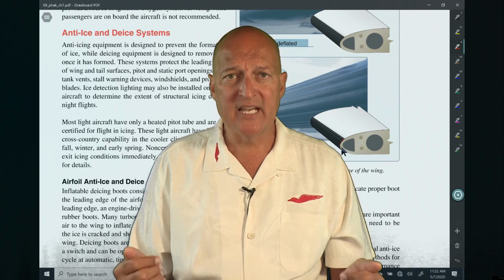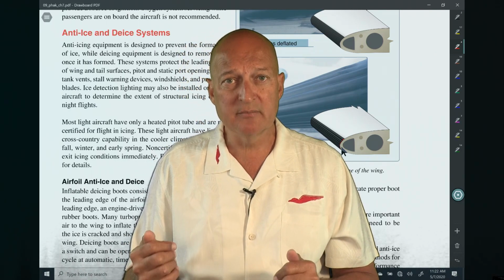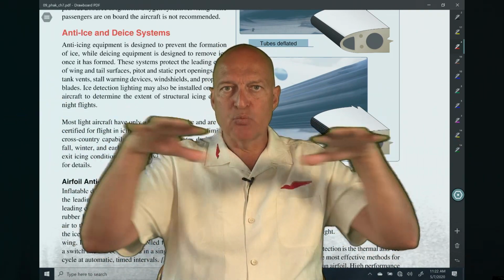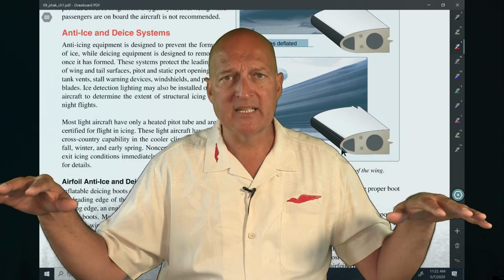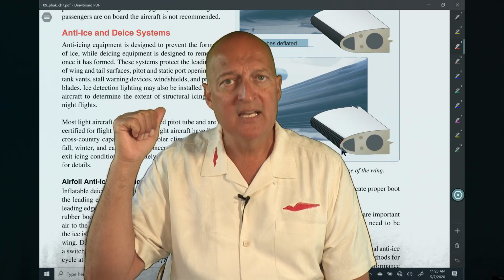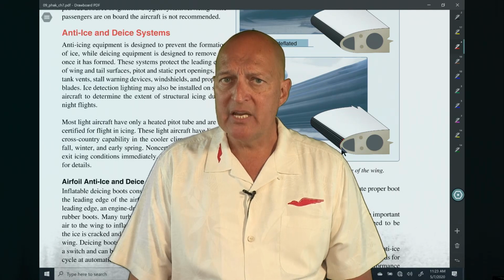Now your airplane is heavier. Think that might also have an issue with your control systems on your airplane? Yep. Because remember, it's not just this wing that's here, usually at the midsection of your airplane, that's going to be collecting ice. You've got this whole empennage mechanism at the back of your airplane that's also getting ice. So now you've got some issues.